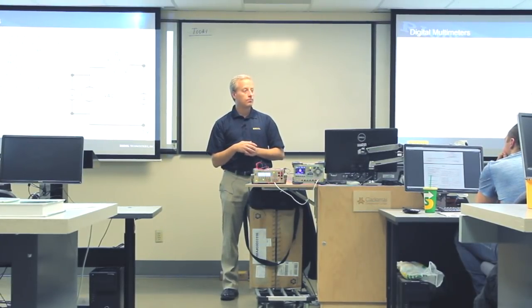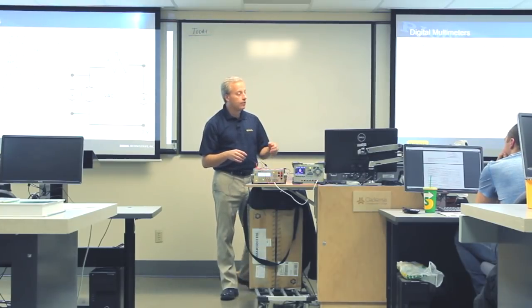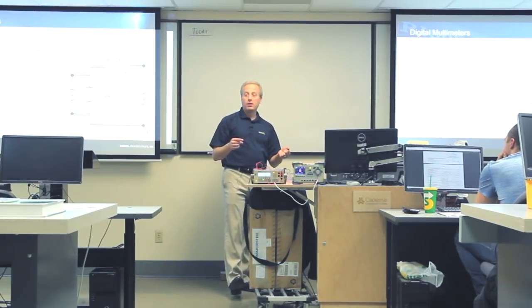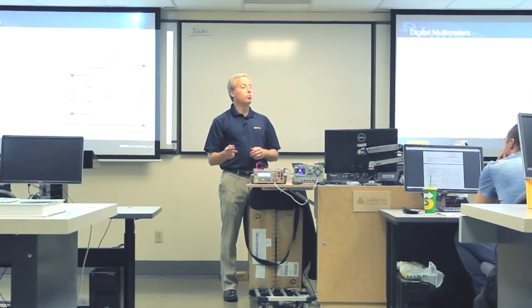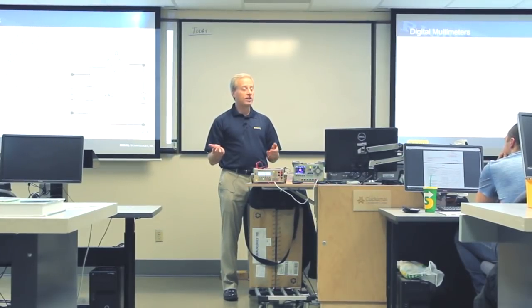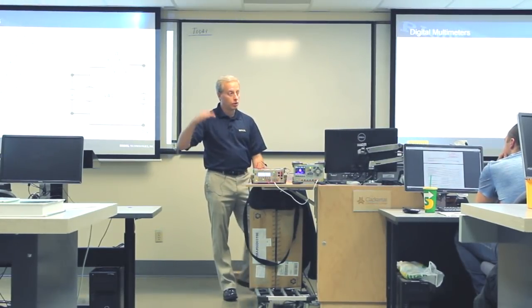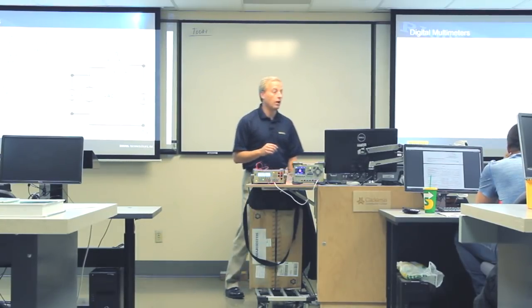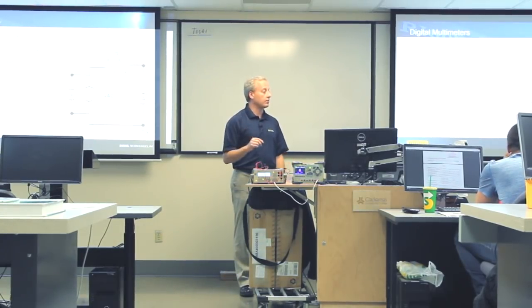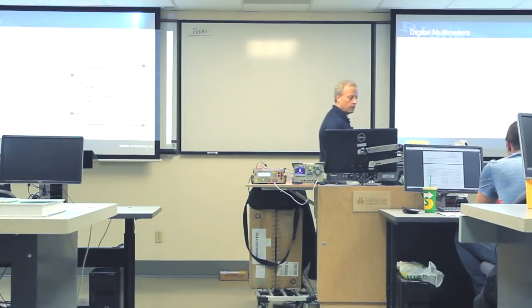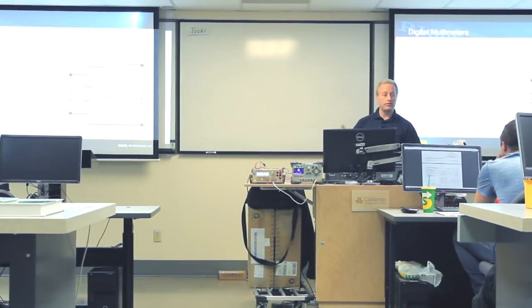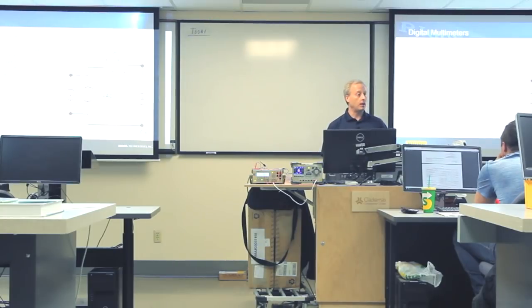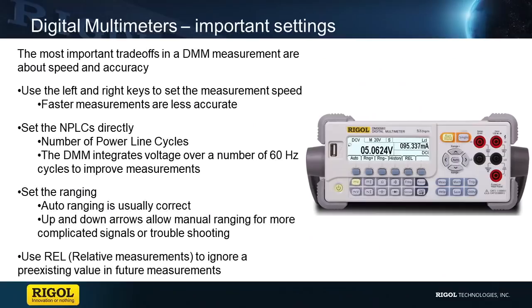So if you're ever doing temperature measurements in this lab, you'll have a thermocouple type J or type K, or other types of thermocouples. It's important to make sure you set the right type, because you're looking it up in a different table for different types of metals. If you don't have the right type, you'll get the completely wrong answer. There you're typically talking about millivolts, maybe even microvolts, being developed on a thermocouple.